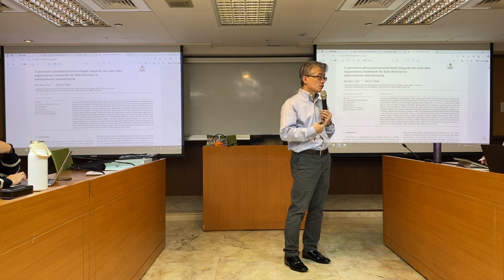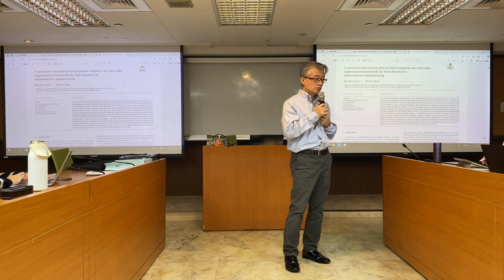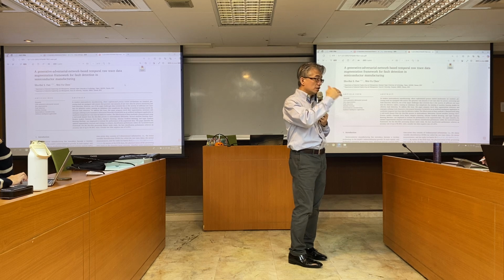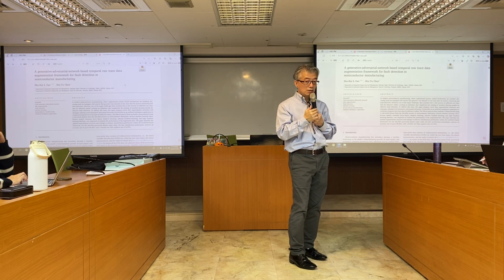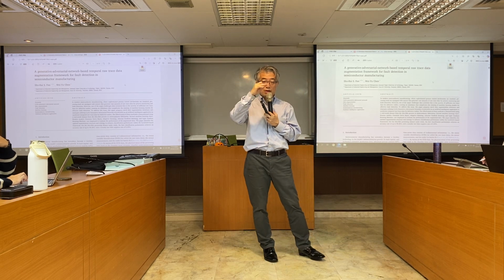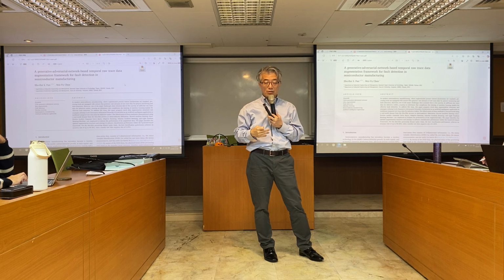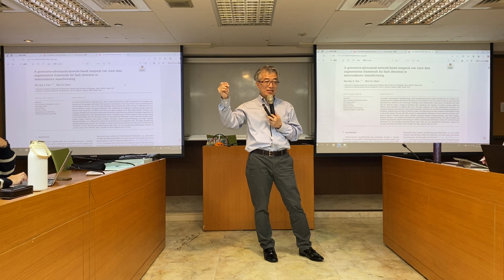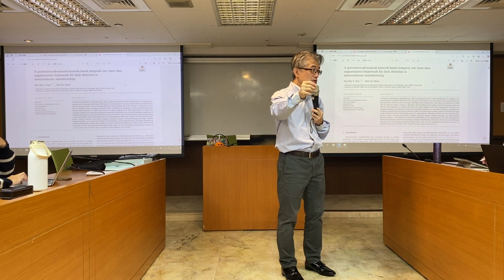Before the era of machine learning, they used the SPC: the upper control limit, center line, and the lower control limit. If any point extrapolates beyond the upper bound or falls below the lower control limit, a signal is issued. That signal is sent to the process engineer.